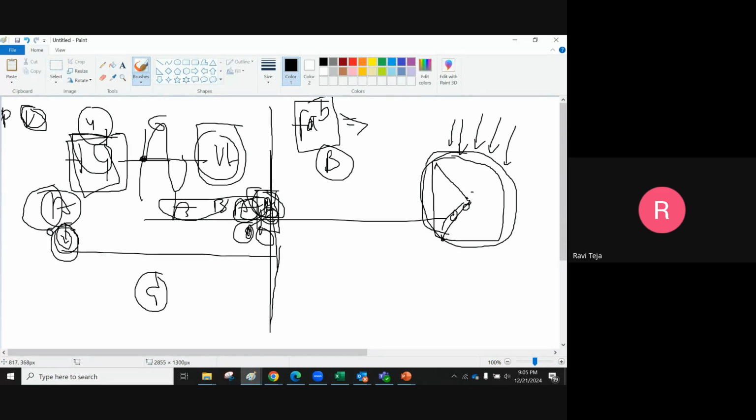That is the most important thing, to match our VTs. All the VTs should be matched, particularly in a current mirror. The current mirror is this, right? The gate is common to all the devices, so VT should be common. Only then the ID saturations will be the same. So that's VT.